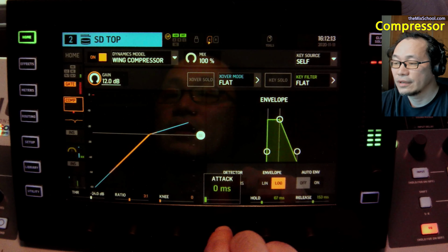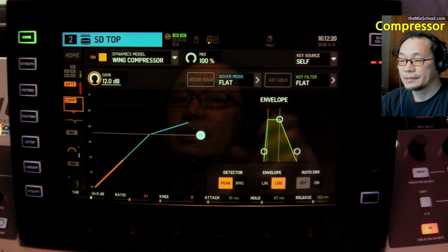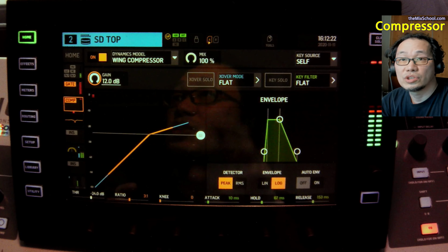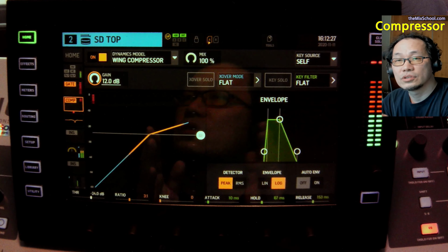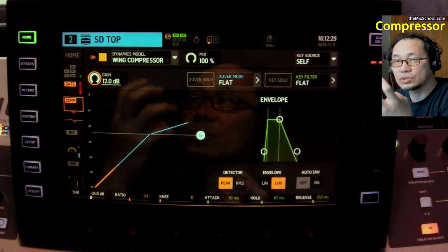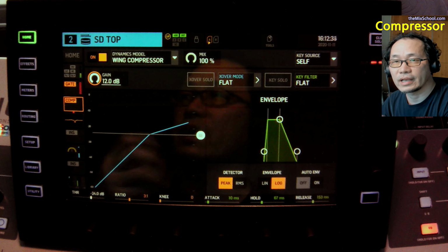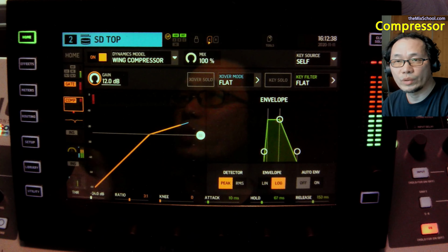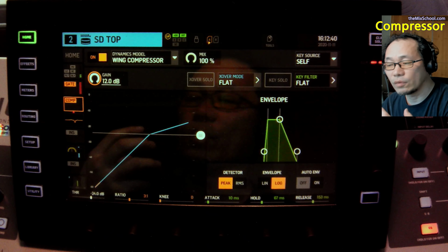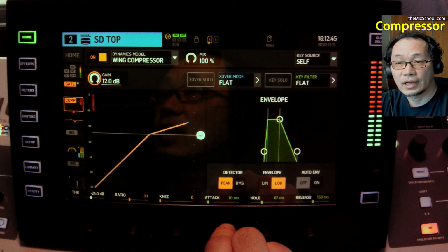If you increase it, the same amount on the ratio will do the job of reducing the volume, but it takes longer. During that longer time, the source envelope and transient energy, like the attack and decay, will just go through without any volume reduction.